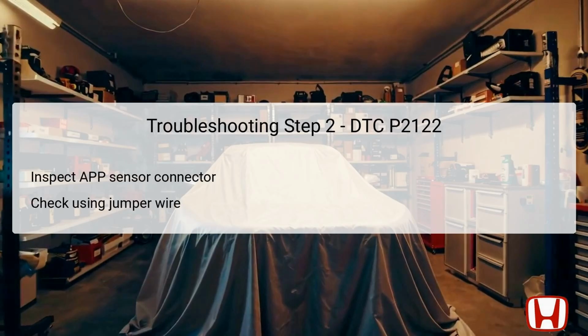For the second troubleshooting step, disconnect the APP sensor connector, which has 6 pins, to begin the physical inspection. The next task is to use a jumper wire to bridge specific terminals within this connector, specifically terminals number 4 and number 6. By doing this, you create a direct path that bypasses the sensor temporarily.